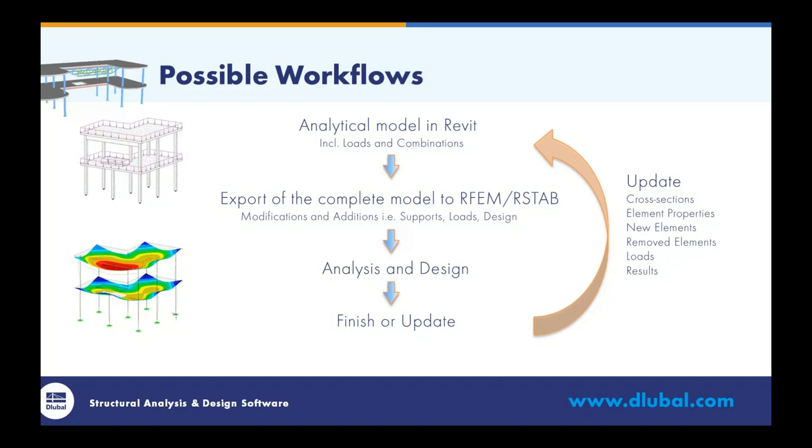And this analytical model can be exported to RFEM, including loads in combination if you want so. In RFEM, you can continue, you can modify the structure, you can add supports, member hinges, loads, you can combine the load cases, and of course, you want to run the analysis and the design.